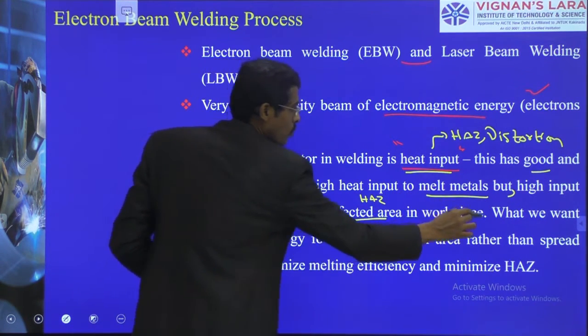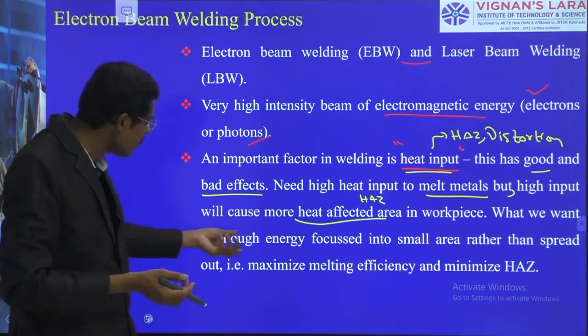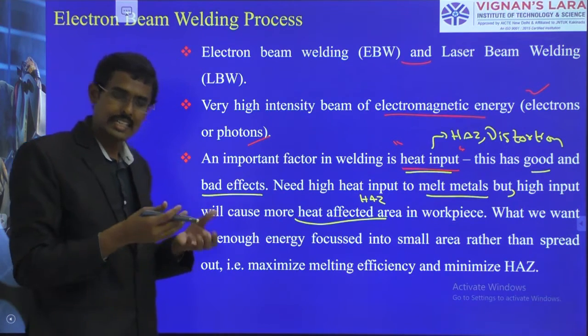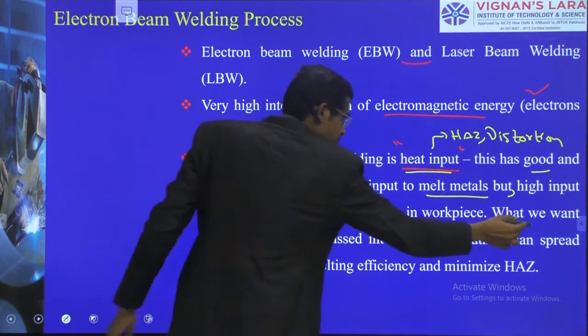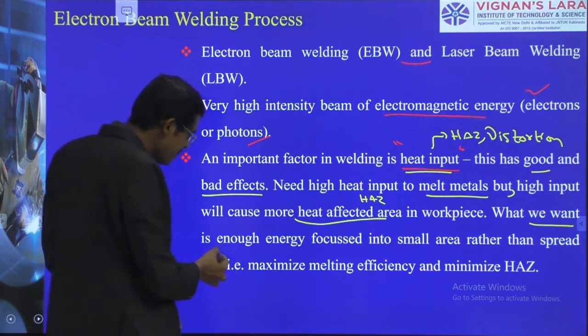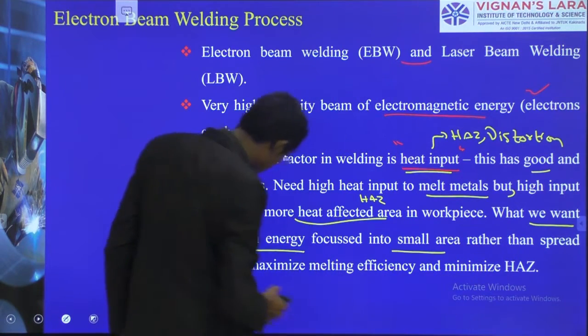But what happens, high heat input will cause a larger heat affected zone. And in the workpiece, what we need is enough energy focused at the gap where we want welding. Therefore we need enough energy focused into a small area rather than spreading out.